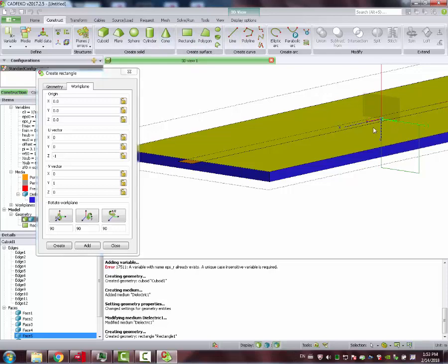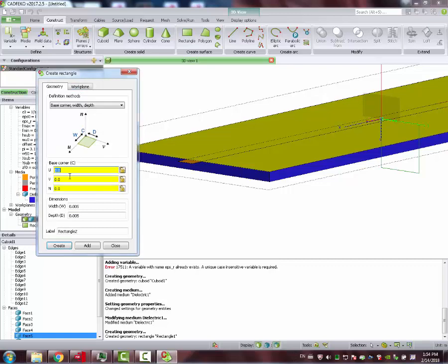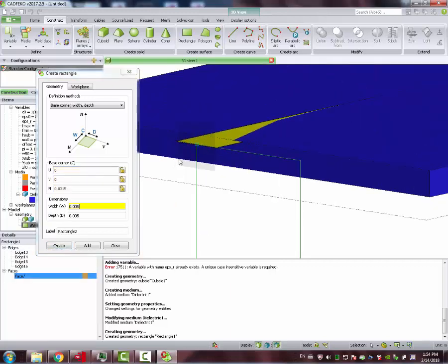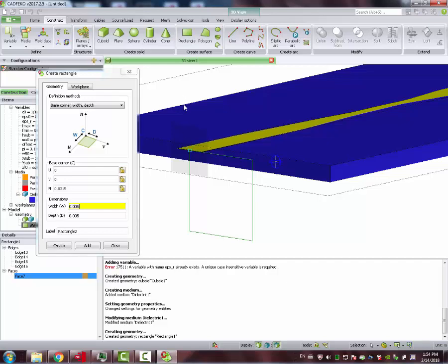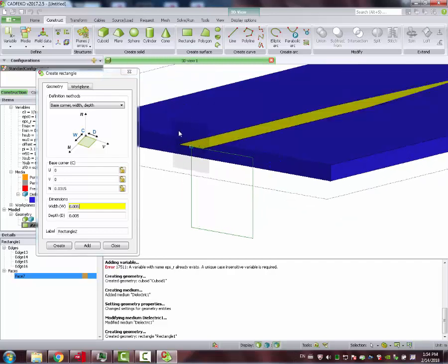So it's consistent with what you are going to construct here. Then we move to geometry, and the active area is this one stressed in yellow. We type in Ctrl Shift, and now using this option here, we pick the middle point, twice. It's done. Now our plane is aligned here. You can see that this shadowed square is showing where the rectangle is going to be constructed. That's exactly what we need.